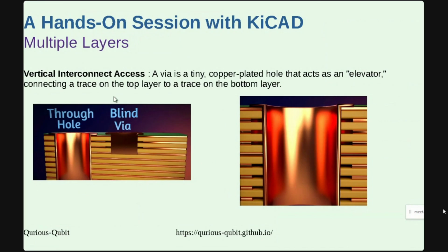But the components which are surface mount may go up to a certain depth itself. So maybe this level 4 is where this particular component is conducting and carrying signals to another component on level 4. There can be a component on level 2 that is mounted and carrying signal to another component. So that's where it gets highly dense.